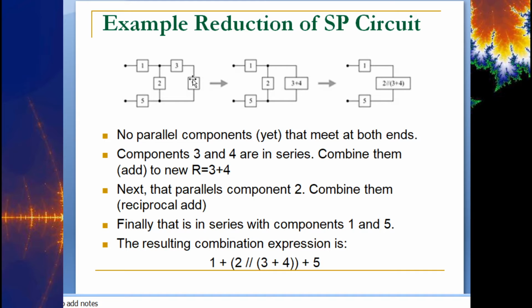So these two are in series with each other on this branch out here. First thing I do is I draw a single resistor for those two. And there we go, okay? I essentially just replace that entire branch with an equivalent series resistance.